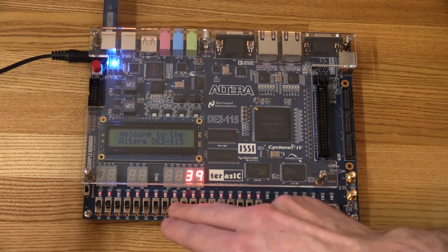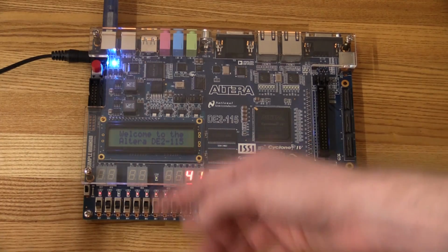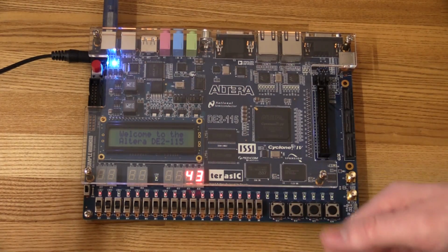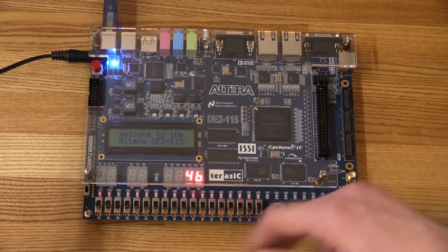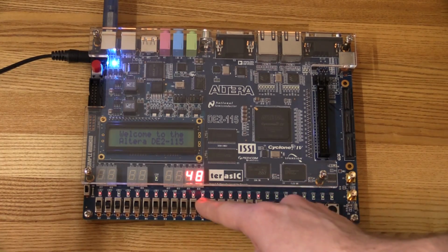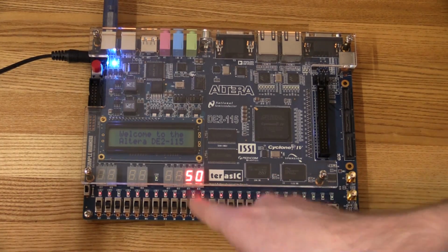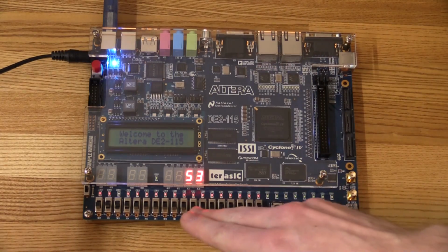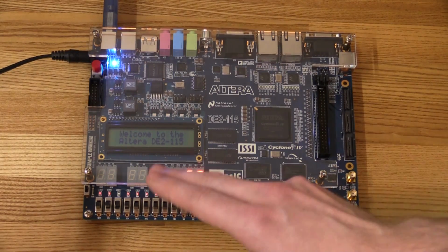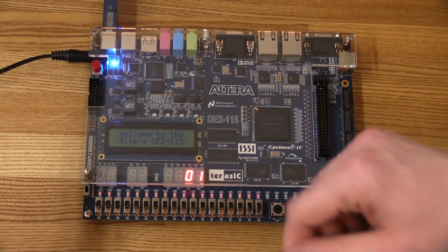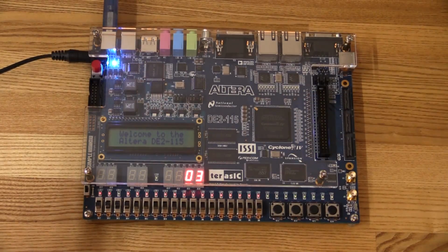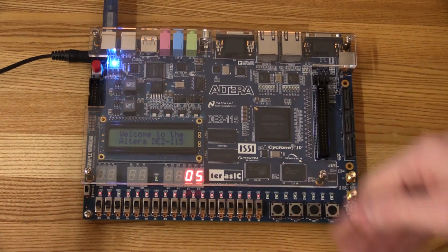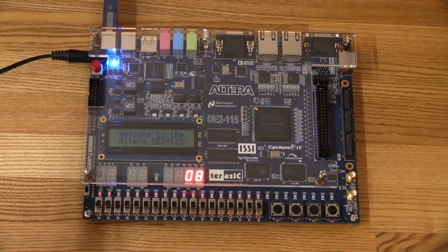As I mentioned earlier, it's easy to see if we get 60 seconds in a minute, but it's not very easy to see if we get 50 million clock cycles in a second or only 49.999999 clock cycles. That's where we use the simulation, because we can see the individual clock cycles on the computer, which there's no way we would be able to just by looking at the LEDs. So that will come in the next video, and it will probably be a bit longer than this one.